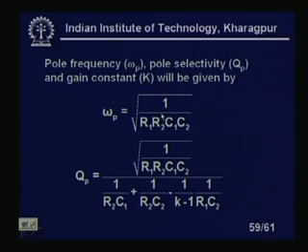So, there is no element which is in omega p but not in Q p, or in Q p but not in omega p. So orthogonal tuning, similarly for K also, if I have to tune all the 5 parameters omega p, Q p, omega z, Q z, and K, it is just impossible to make orthogonal tuning with the single amplifier structure. That is a great drawback.